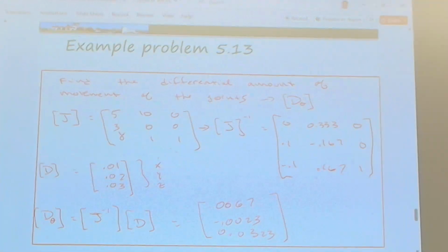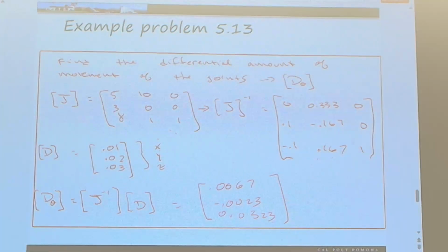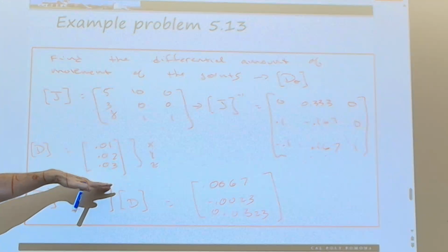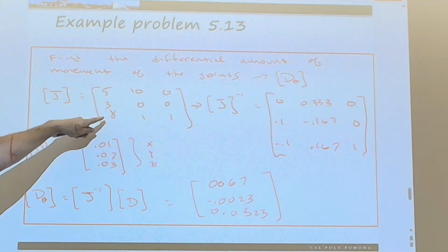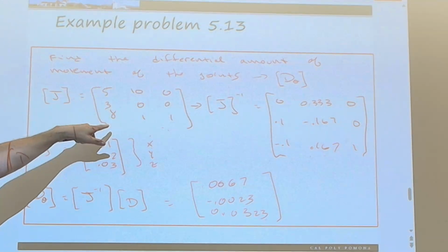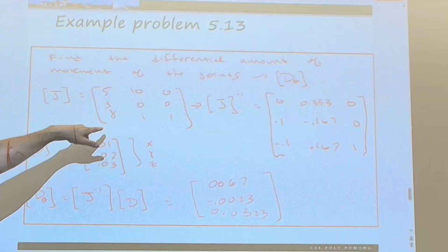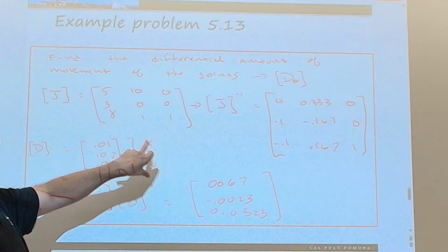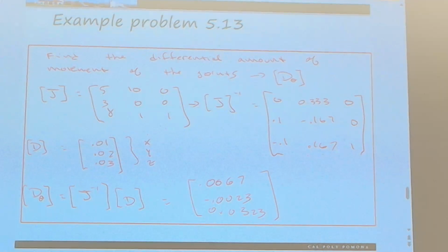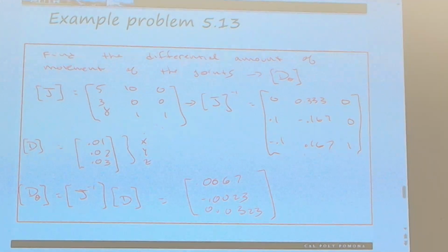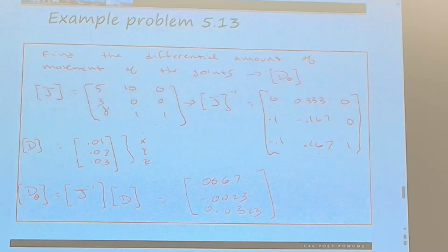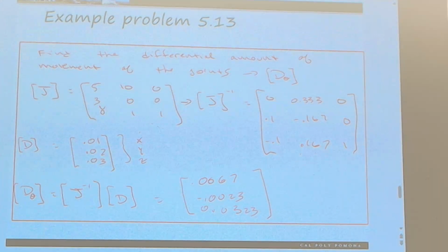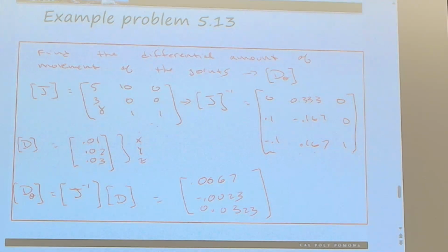And it was only an x dot, y dot, and z dot. Those are only 3 of them. I could have asked for about x, about y, and about z if we wanted to. If we did that, then our Jacobian would have to change to reflect those relationships. It'd be 6 by 6? No, it'd be 3 by 6 or 6 by 3, depending on how you look at it, because this is still only 3. So there doesn't have to be a square matrix. Jacobians don't have to be square. They're not orthonormal. Jacobians are not orthonormal.